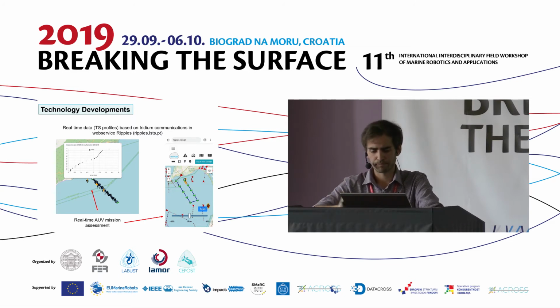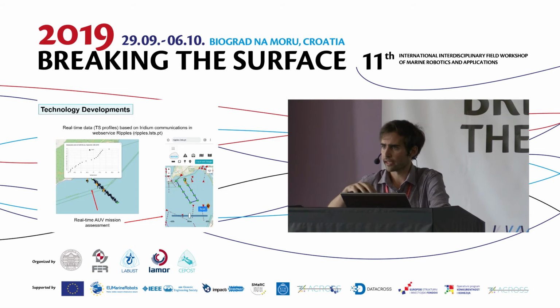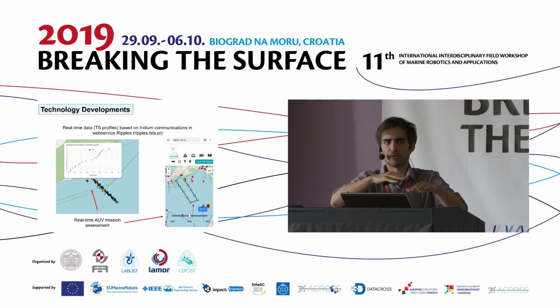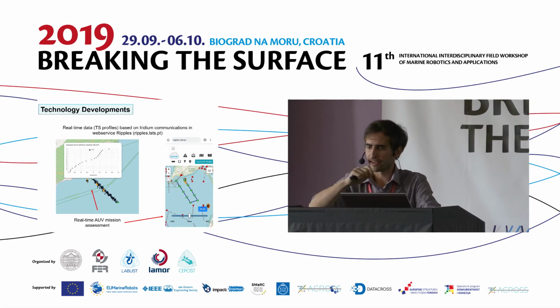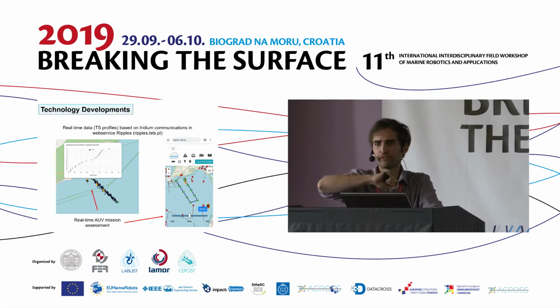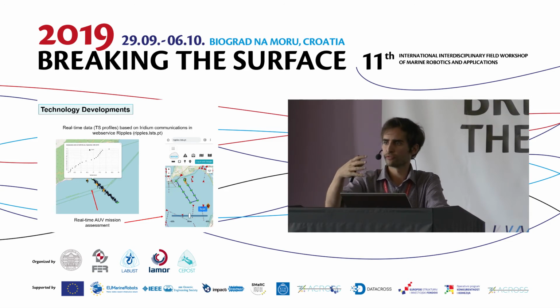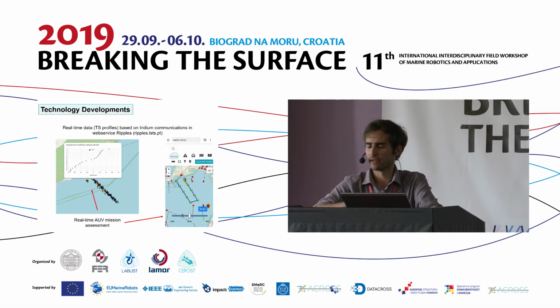plan for the AUV. We also developed a NetCDF feature to upload files like satellite images as layers on the Neptus command and control. So like me, as an end user, I can command the AUV over a map of ocean data. So I can do the plan over a front on the satellite image, and for me, it's more visual to see the AUV plan on that.